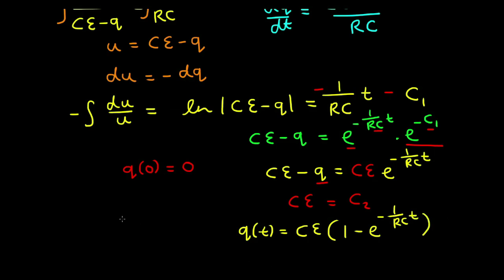And what we do is set tau to be equal to the resistance by the capacitance, and rewrite this expression as e to the negative t on tau. And this is the solution to the ODE that predicts the charge on the capacitor when it's charging. And we'll analyze this solution in more detail.